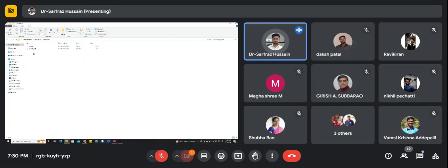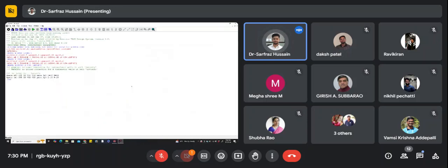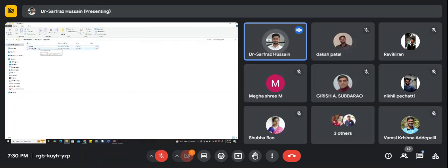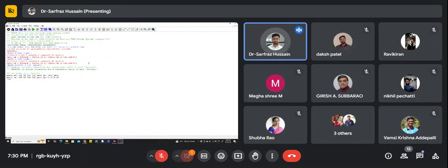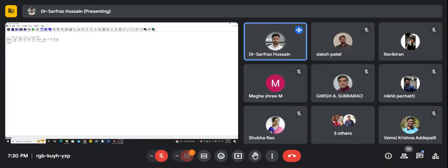Now, if you check the programs folder, there you have this SPI file. This SPI file, we can open it up in LT Spice. If you go to the programs, you can see that the inv.spi file is generated. Now this inv.spi file we can open in the LT Spice environment. When you open it, you see all these notations, right? Options like this, everything written, then the model of NMOS is given, level 1, PMOS level 1. These things you can delete, as they are not required.